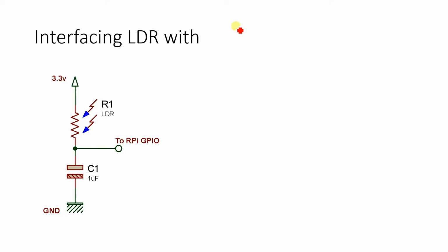So the very first step in our program should be that this particular GPIO pin will be made output. We are going to read it as input, but first let's make it output. In the second step, we write a false value onto the output, which will write 0 volt onto the output.